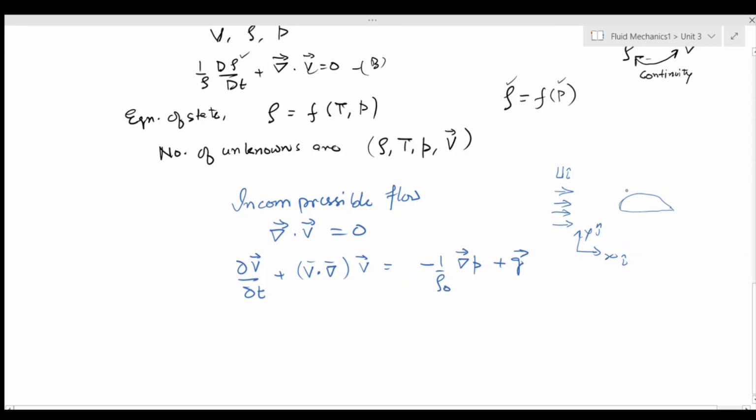But once I come near this aerofoil, at different values of x and y, each point which I am showing here represents a coordinate point. Now at each of these points there would be some velocity vector. So basically, if I am writing my velocity vector and it is changing in any way, let's say a x i plus b y j, this is known as the velocity field. Many a time it is easy to find the velocity field experimentally or through equations.